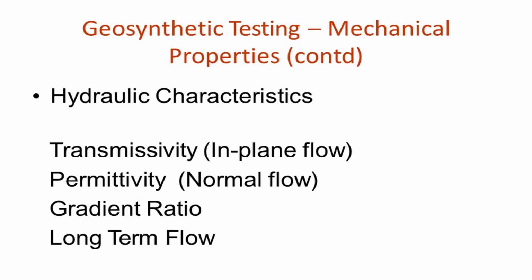So that is for friction now. Then for hydraulic characteristics, we are going to think of in-plane flow. It's called now transmissivity. That means the actual flow characteristics along that, the drainage characteristics, are measured along the plane. And remember this word now, in non-dimensional form, transmissivity. This will be defined later. It will be non-dimensional form. That means non-dimensional doesn't consider the thickness then.